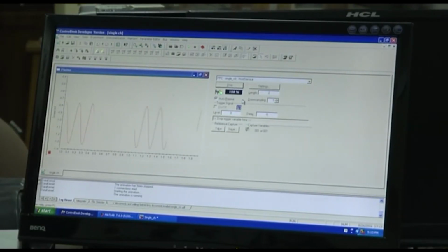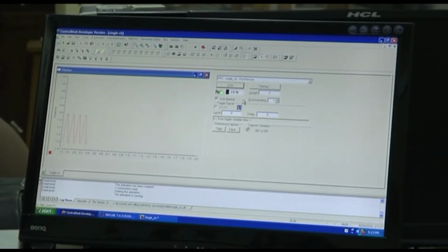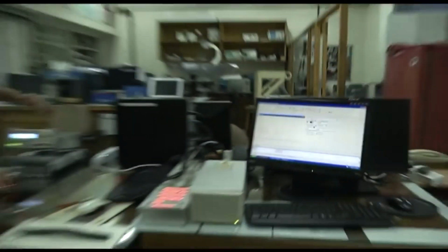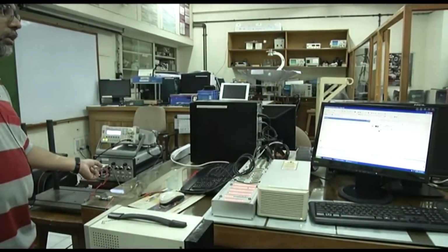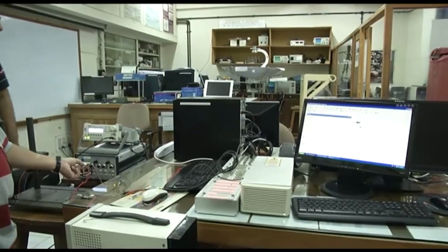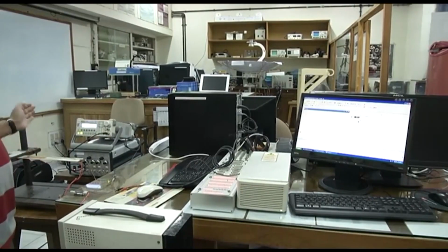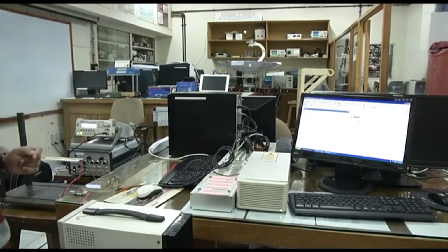As we change the frequency, we will see that this amplitude is going to slightly come down because we are lower, below the resonating point. And also if I hold it, constrain it, we will see that it is coming down. As you can see, the sensor will immediately sense that there is something which is holding the vibration, and hence the signal will actually come down. So this is how you can use the MFC both as an actuator as well as a sensing system. Thank you.